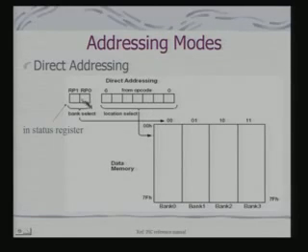So these 2 bits are used for selecting the bank, and the offset in the bank is specified by these bits which are part of the instruction. Therefore, in each of these banks I can select a location by specifying this 7-bit address in the instruction itself.